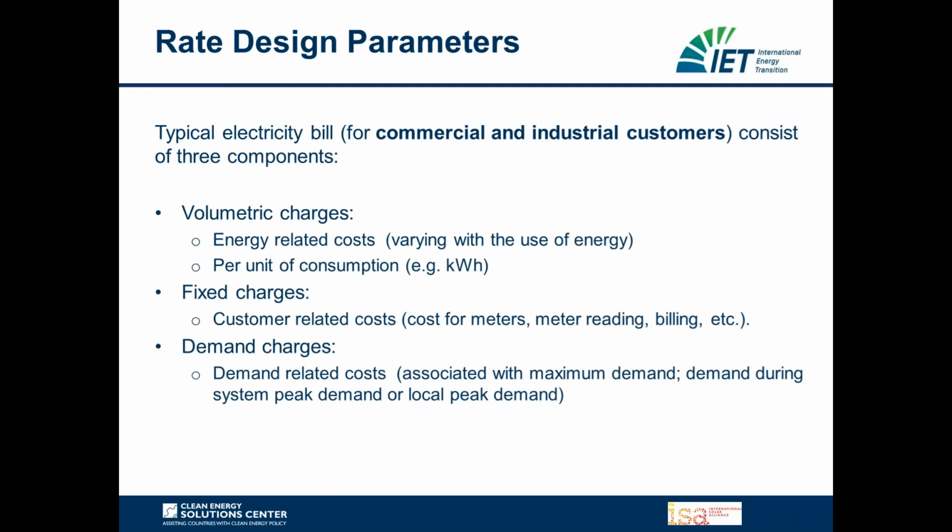When you look at larger scale commercial customers and industrial customers, you normally see a three-part electricity bill composed of volumetric charges, so per unit of electricity consumed, fixed charges, as I mentioned before, related to metering and billing. And then also we usually see demand charges implemented, which are usually associated with the maximum electricity demand of a certain customer over a certain period of time.